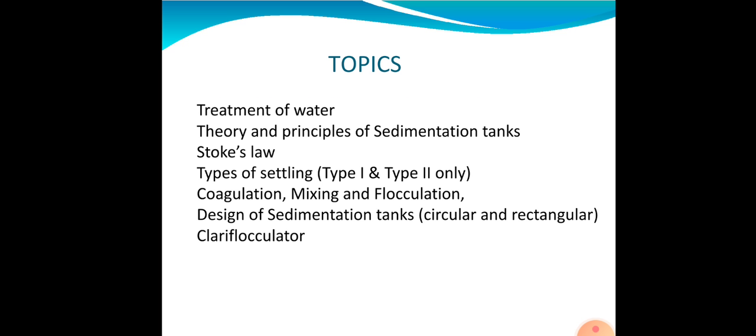These are the topics that we shall be discussing in module 3: treatment of water, theory and principles of sedimentation tanks, Stokes law, types of settling. Mainly we'll be dealing with type 1 and type 2 settling, coagulation, mixing and flocculation, design of sedimentation tanks. Here we will be discussing the design of circular as well as rectangular sedimentation tanks, and Clariflocculator.